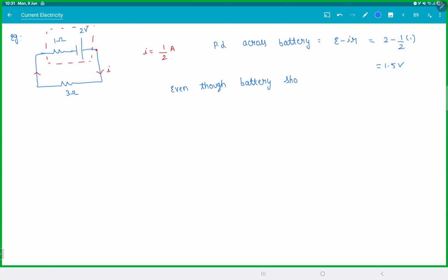So it actually depends on how much current you're pulling from the battery. The more current you pull, the less potential you get. That means the current depends on the external circuit. So depending on what kind of circuit you're connecting, you get different potentials there. So the ideal battery which we had, which didn't care about the external circuit, in real life, the battery actually cares about the external circuit. Depending on what you're connecting, your potential gets messed up. You pull too much current from the battery, it actually doesn't give the voltage you want.